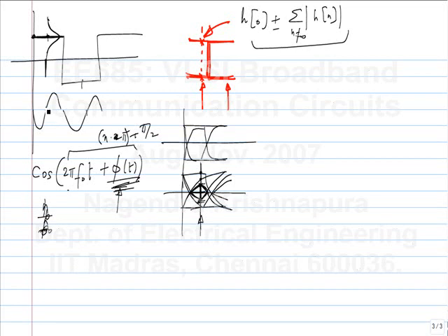So it can sample here with a high probability, but there is some probability that it will sample somewhere in the wrong bit interval. Because of jitter, the clock edge will move around, and it can be shifted so much that it is sampling in the previous bit or the next bit. That is entirely possible. The probability of that depends on the variance of noise. Now if it samples in the wrong bit, not the current bit but either the previous bit or the next bit, and let's say the data is completely random, there is a probability of half that bit is in error.